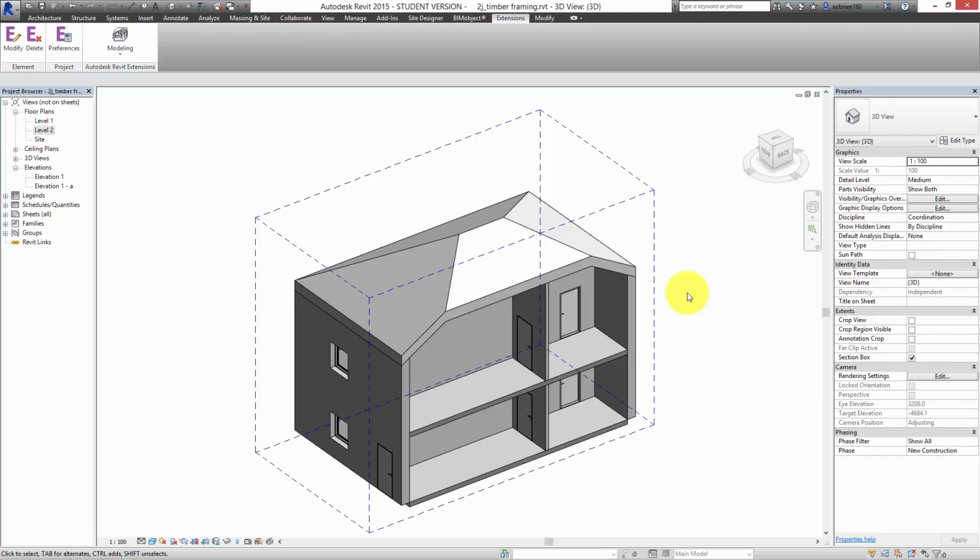But for European walls, which are twice, 3 times as thick, the timber framing extension doesn't really work that well. So if you're using it, you need to first of all understand that this is the case, and you might need to make a copy of your model with a thin wall, like an American wall, in the right position. It would make more sense if they remade it so that it built the timber frame inside the structural layer of the wall.